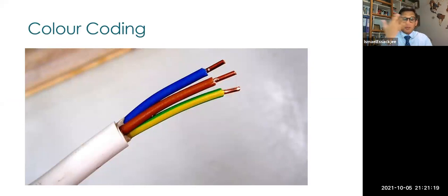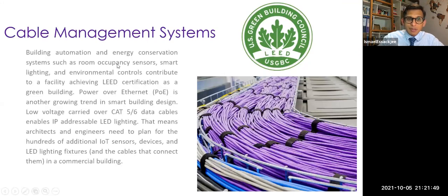So be careful. Why is it so important? Well, let's say you are interconnecting the relay. Will you connect it to the neutral or to the live? Be very careful about it. You should always connect it to the live, not the neutral. So be very careful. The neutral should be going through. The live is where you have the relay inserted, and this is going to control when you switch on or off.